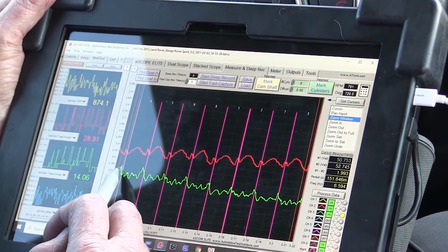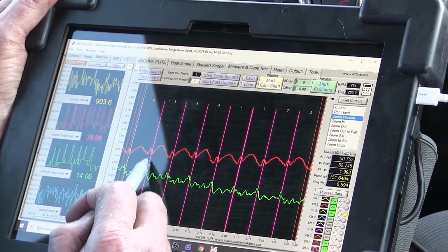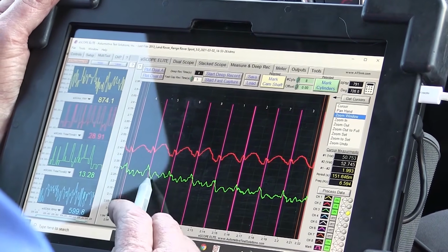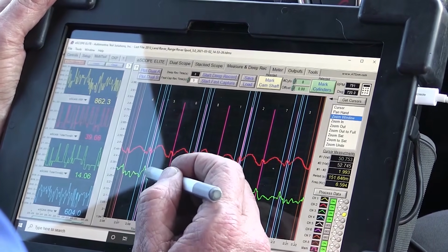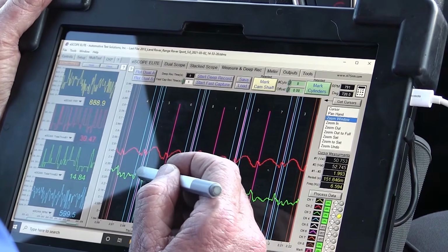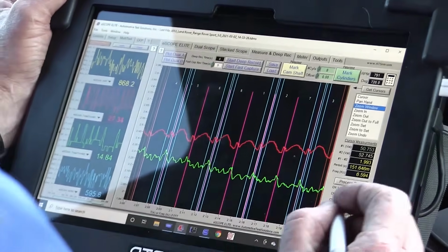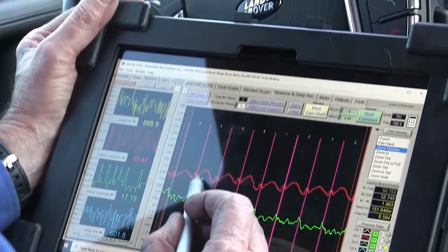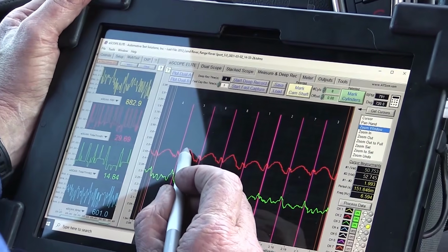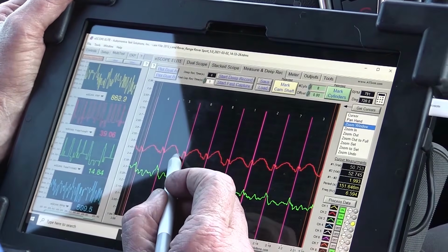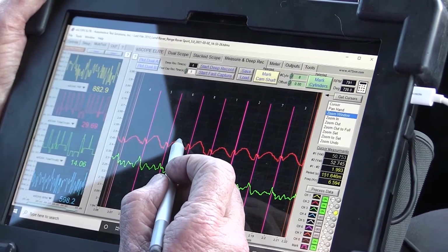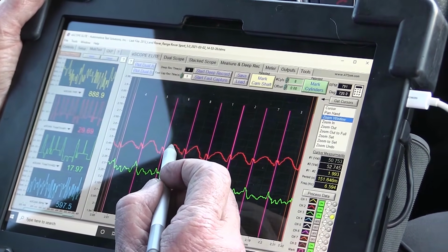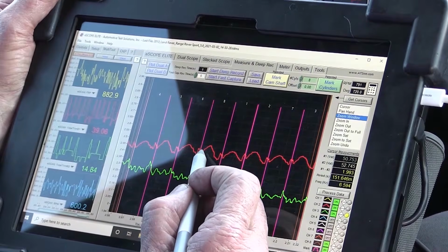Now what I'm interested in right now is the low pressure line. I close the valve, and do you see how I get this drop? Well, that drop happens when I shut off the pump. So I'm shutting off the drive, and that opens the valve, and then I get this pressure build, and then the next pump is going to turn on, and then we fire, and then we open the valve, and we're bleeding up the pressure back into the main rail.